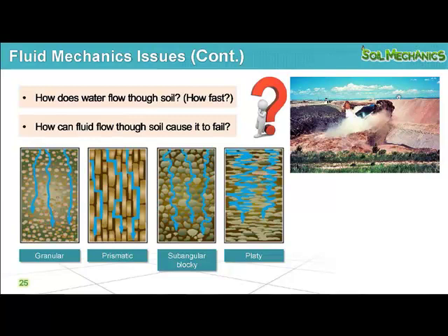If the construction material or soil that we use for this earth dam is not good, or the design is not good, it will fail due to factors like soil bearing capacity failure, or water flowing through the soil, and other modes of failure.